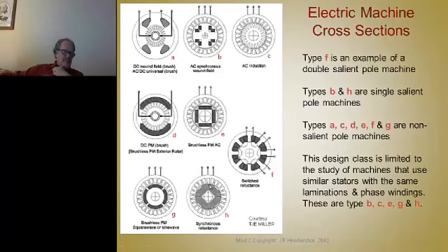It's made up of pieces of steel and air, or steel and plastic, or steel and magnets even. The steel parts are called magnetic flux carriers, and the air sections, or plastic sections, or fiberglass sections, or whatever you want to make them out of that's non-magnetic, those are called flux barriers. So if this is a direct axis, the inductance of the phase windings in this axis is high because there's lots of iron in the circuit, but in quadrature, or 90 electrical degrees, this is a 4-pole machine, so it's 45 degrees mechanical. This is a quadrature axis, so the inductance of the phase is low in that axis because there's a lot of flux barriers radially from the shaft out in that quadrature direction, you see.